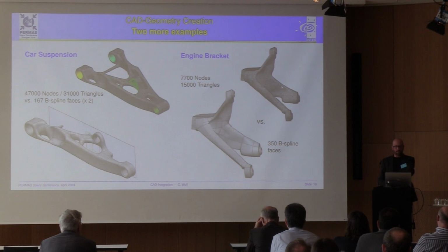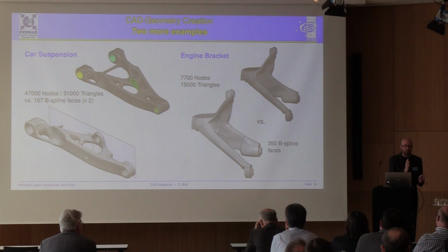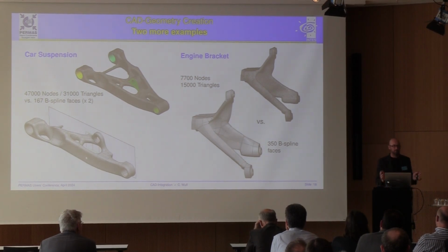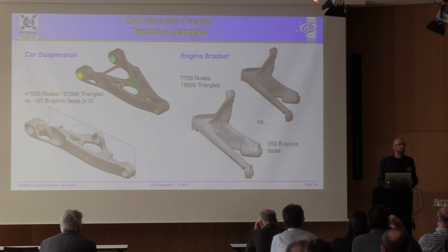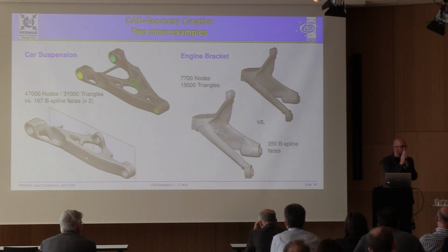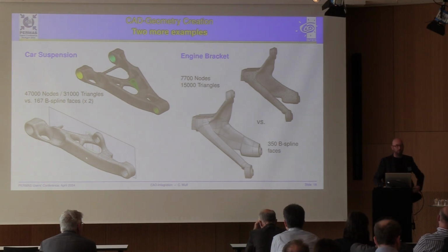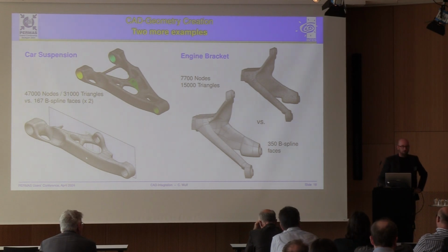This is why in this case you see here, I just took the half model, and then later one can build the symmetric model. Although you cannot do this always. Sometimes you have loads that break the symmetry, then you need to maintain the full model. For the moment, it's a workaround, because up to now we don't have the possibility to enforce the symmetry in this process. I get it. This is also subject to future development. This will be possible in future, probably. Hopefully, yes. But difficult.